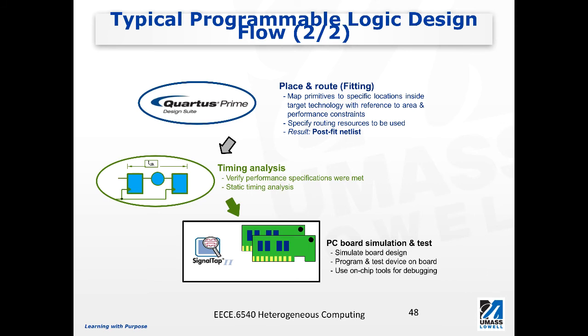At the last stage, the developer can take the design and run board level simulation or even load the design onto the actual board to perform the desired function and also to verify the results. There are tools such as Signal Tap that can be instantiated together so that the triggers can be fired, and that will help the developers to debug any issues if there are any.